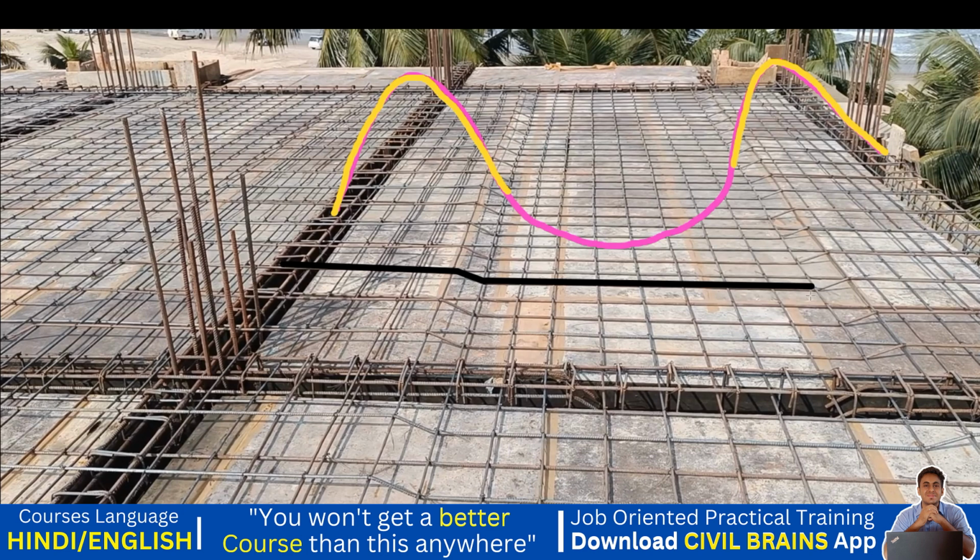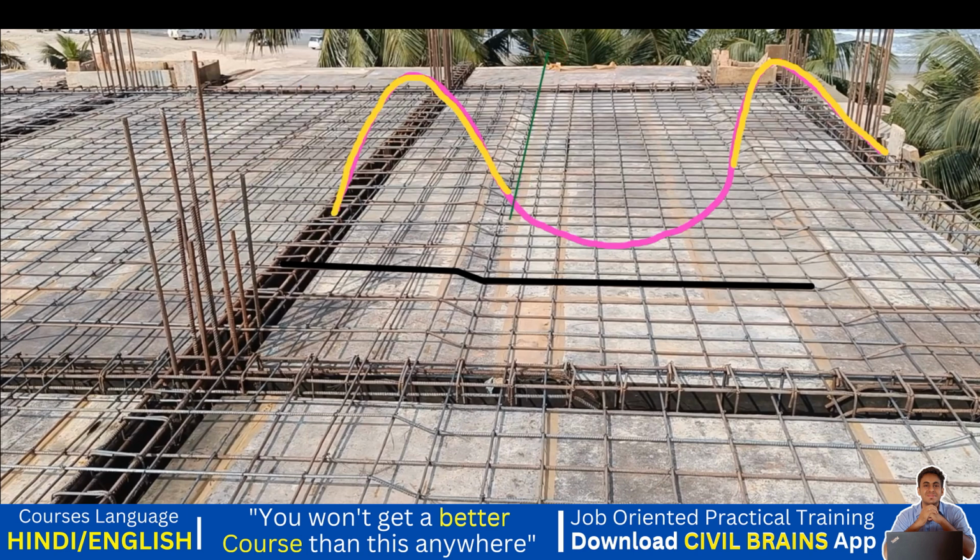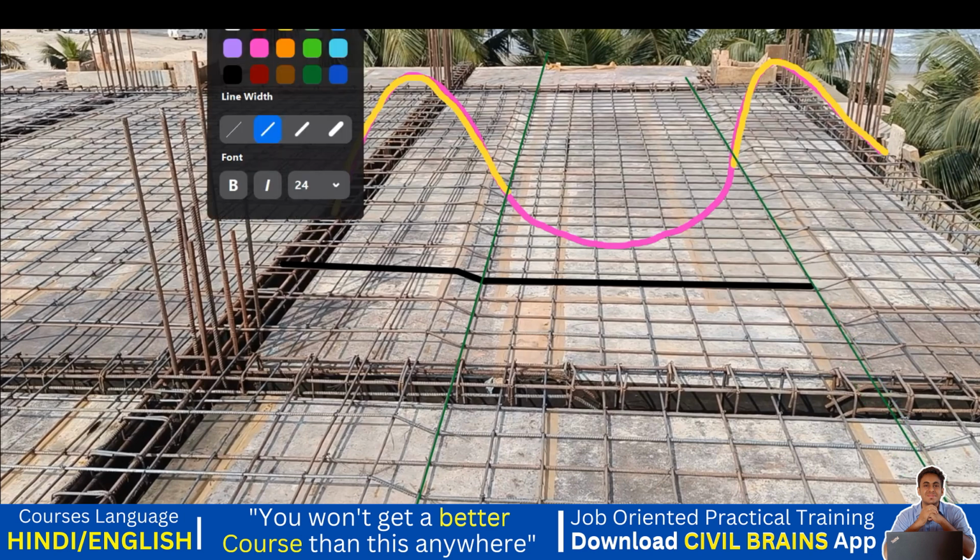Getting my point? Similarly, this was my cutoff point. From here my slab was trying to lift up, right? You can see this bending moment diagram. If you want to put it in a clear way, let me do it this way, so that we don't have any confusion left after this. I'll take this as my cutoff point. This is my cutoff point, where my bending moment is changing the sign, and similarly this is also my cutoff point where my bending moment is changing the sign. Now we are in a better position to understand that.